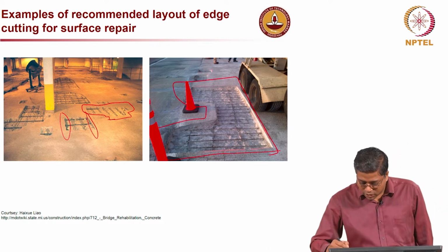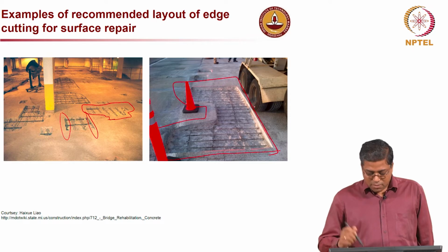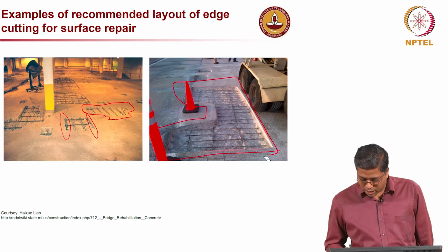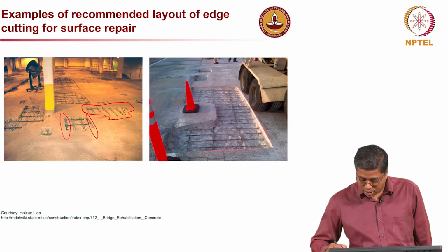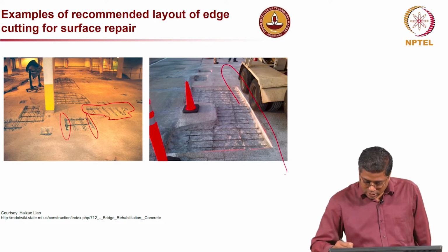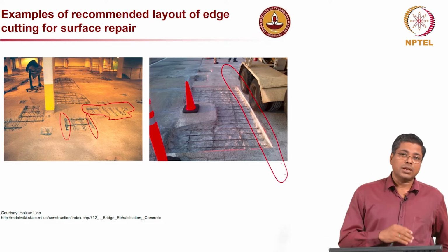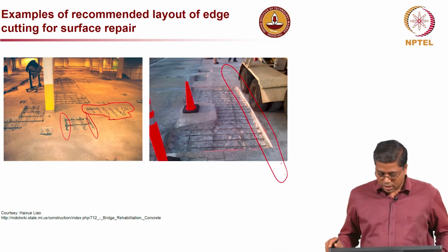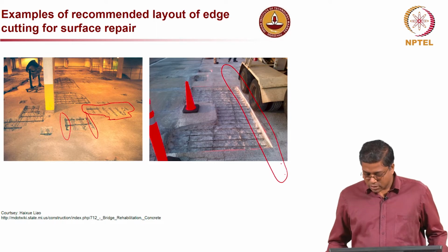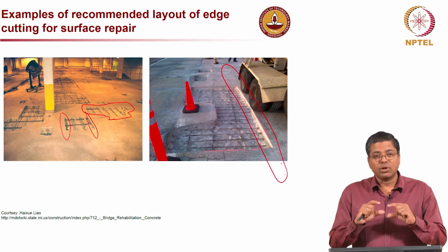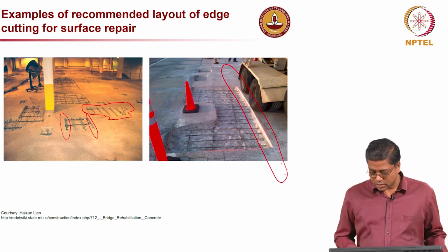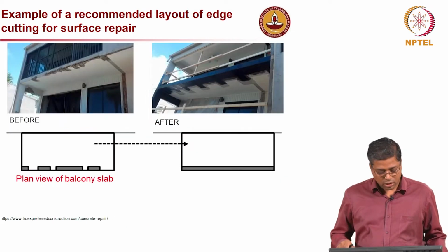Now, when you make these cuts, make sure that you do not cut the rebar, as you see on the bottom right, on the right side image. If the cut is deep, then you may cut the rebar also, and that must be avoided. So, that is something very important. The depth of the saw which you use is very important when you talk about this.